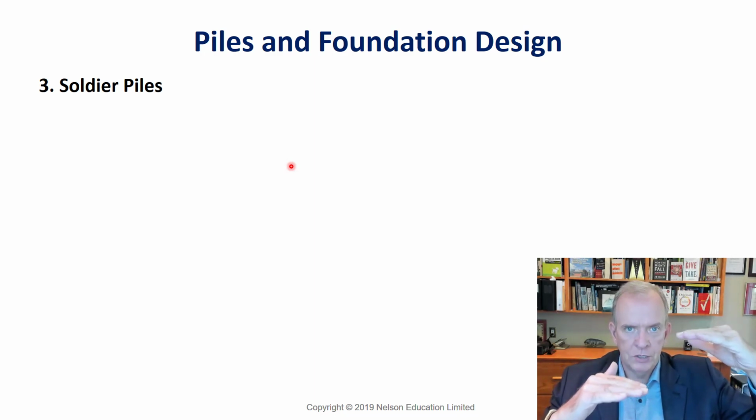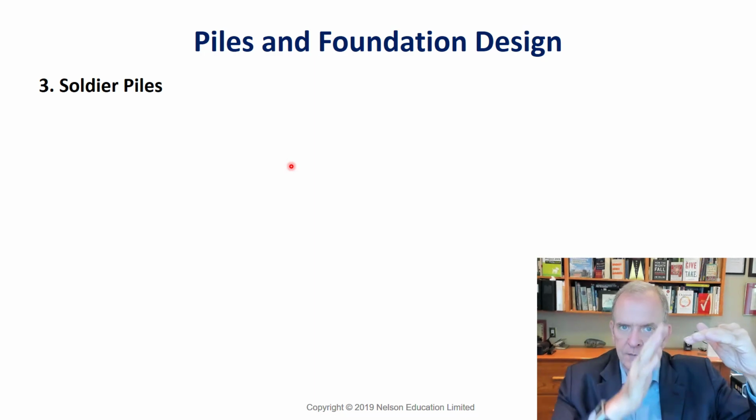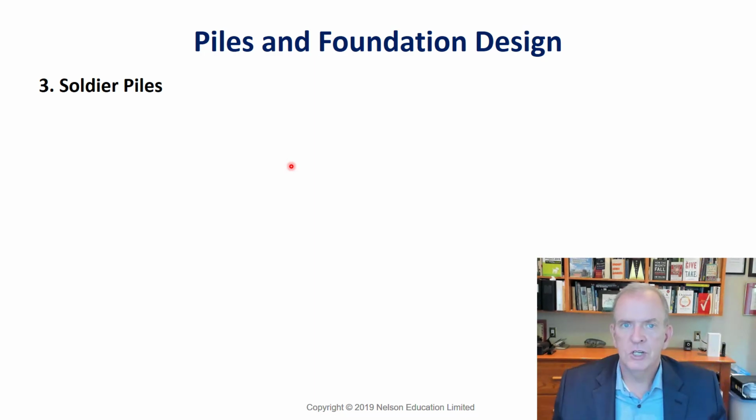So if that foundation is a lot lower than the one next door, then this weight, when you excavate down, it could put that house in jeopardy, because that could crumble the soil. It wouldn't be able to bear that capacity. And if that starts to settle, that house is in jeopardy. So to protect that, in some cases, you might have to put a row of soldier piles and lagging to prevent any settlement of the property next door. So there's different designs that are utilized that way. So soldier piles is used for that in that example.